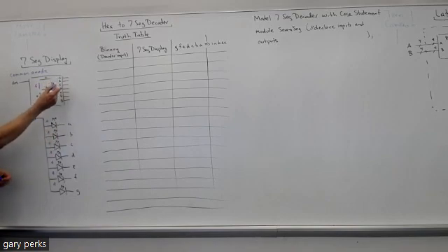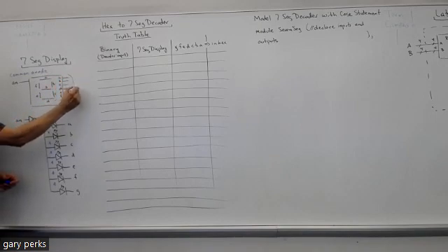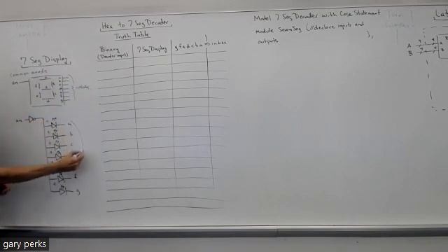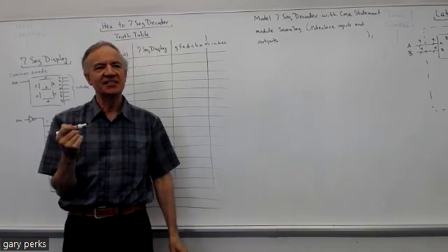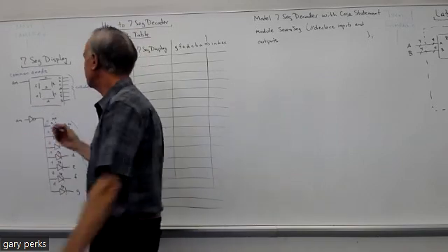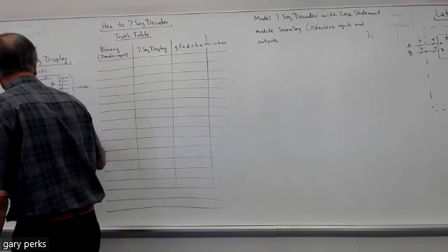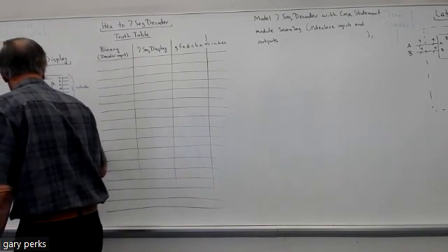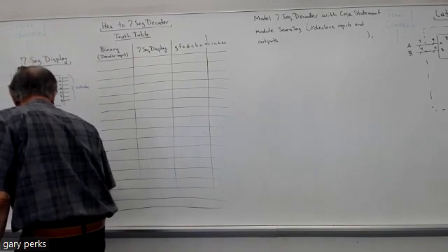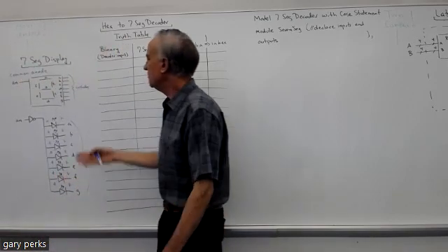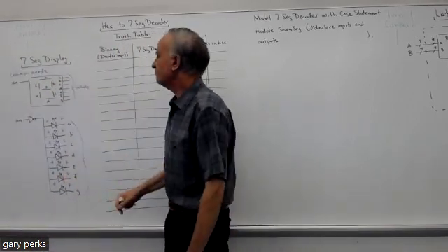So, the A, B, C, D, E, F, G over here, these are cathode inputs. Right, so all these are cathodes. Does anyone know what letter we use for cathode? K. Yeah, we use K. We don't use C. Why don't we use C? Yeah, capacitors. Yeah, cathode we use K, even though it's spelled with a C. Okay, so, you know, each segment is an LED.